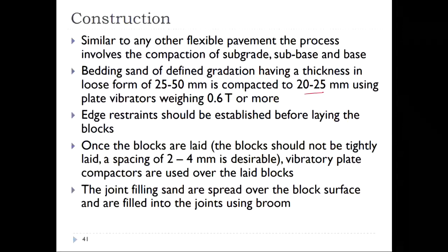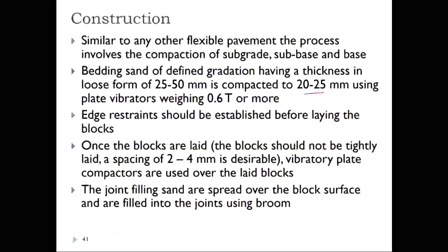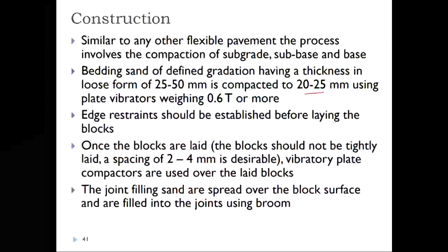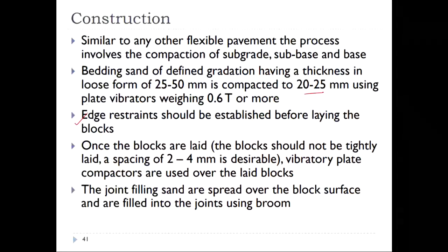You can use plate vibrators. Your construction is mainly a manual operation, so you need to use plate vibrators, or you can use vibratory compactors so that you are able to speed up the work. Now, edge restraint is one of the major things. Edge restraint should be established before laying the blocks. Once the blocks are laid, they should not be tightly laid. If the blocks are tightly laid, you will find difficulty in filling your jointing sand.